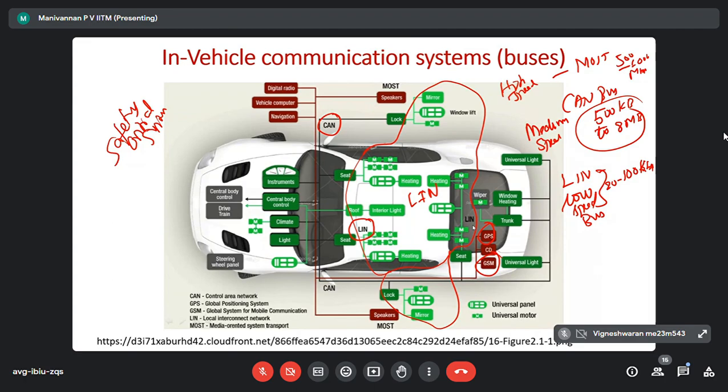when you steer the vehicle in a sharp corner, if the steering control doesn't sense that you are steering sharper, that means you are going to steer your vehicle very fast. Now, the rate of steering angle, if it's not sensed in milliseconds, and if the steering assisting motor is not immediately actuated, your vehicle will go off the road, you will get killed. So that's why they call it safety critical.